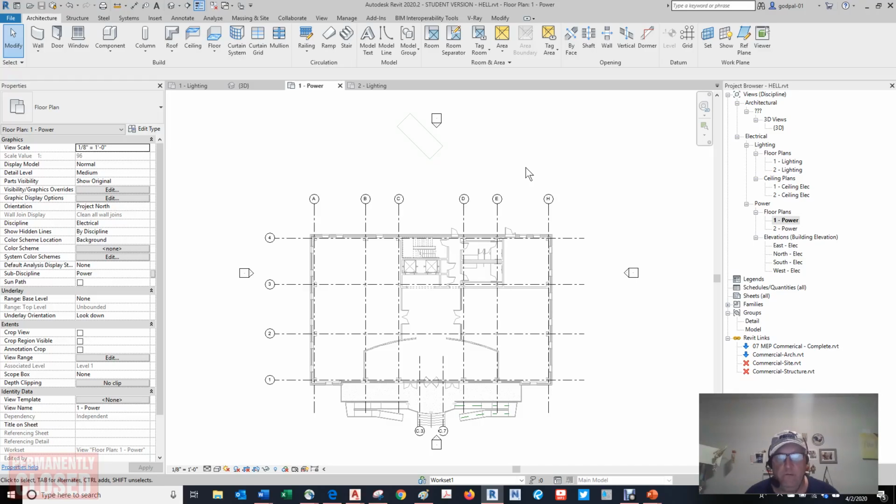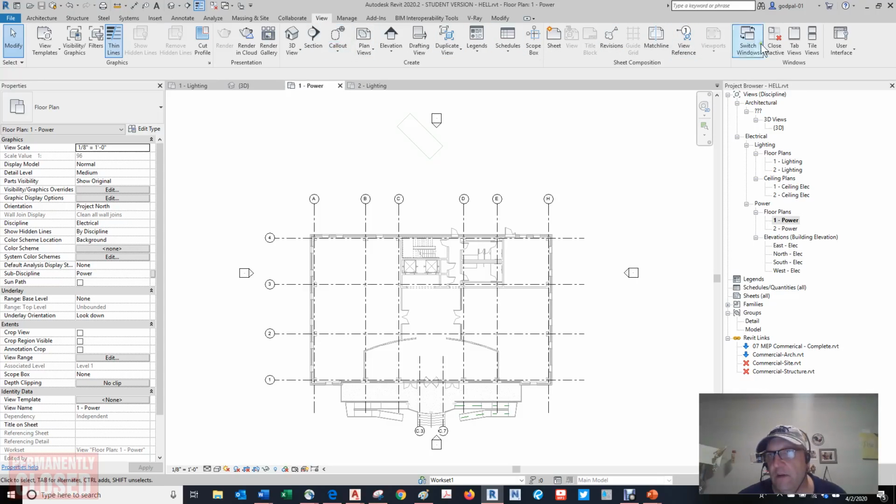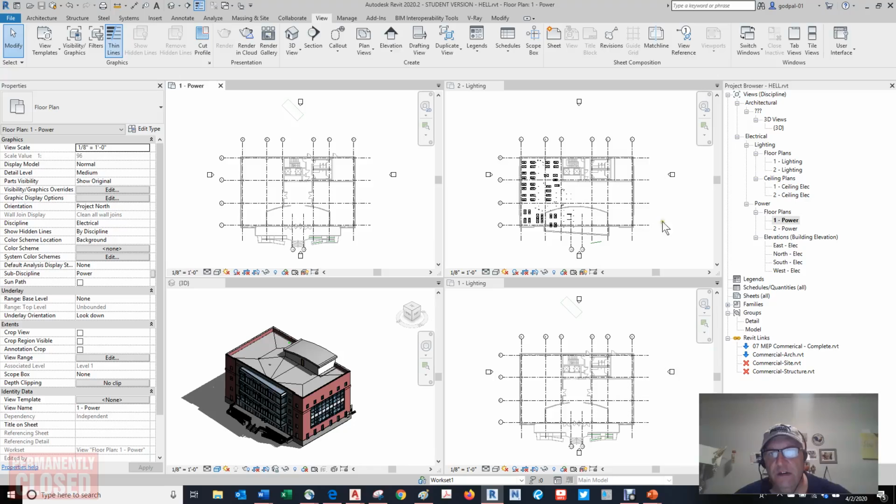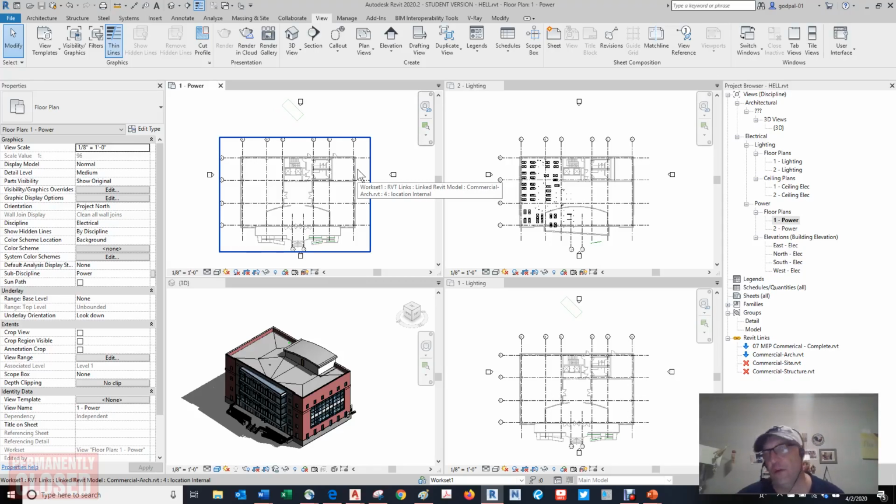The drawing area is the window into your design space. As shown previously, you can tile multiple views, and if you miss that, as you can see, I have 4 views open. If you go to View, and you go to Tile Views or Tab Views, you could tab the views and hit ZA. You can zoom on the keyboard. A shortcut key is ZA.